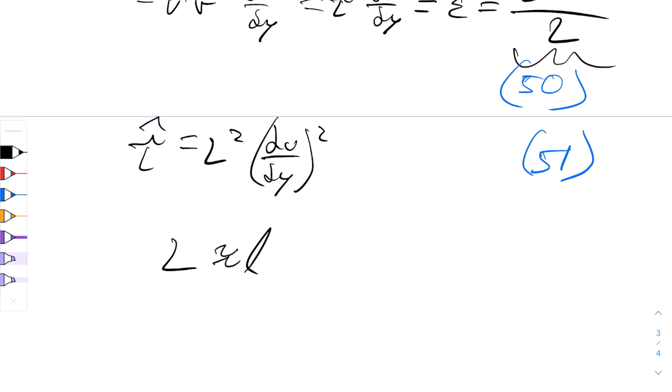we have this case. Now, the turbulence can be assumed to be determined by the largest eddies, which have a length scale L, and these cover most of the boundary layer, as I noted in our notes in the beginning, from 0.25 to 1 for y over delta. And therefore, a characteristic velocity of the fluctuations would be totally determined by the local Reynolds stress tau hat. The diffusion would be characterized by the gradients in tau hat, which can be represented by tau max, as I noted before. This means the maximum value of tau hat